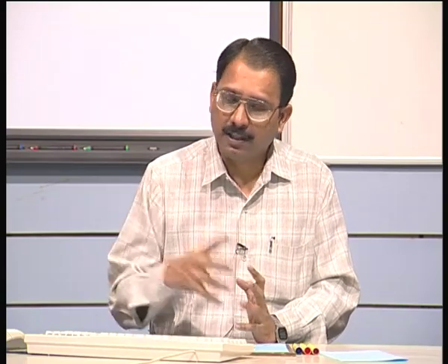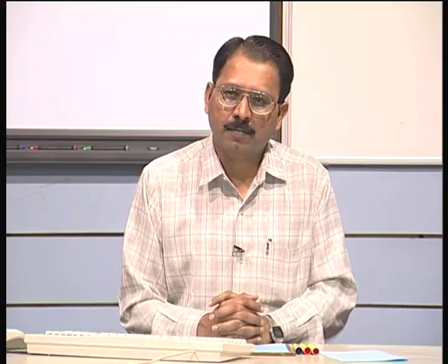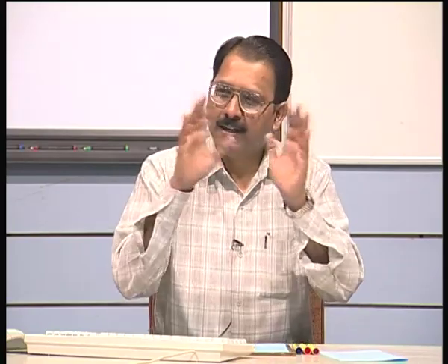So, there are situations where voxel based decomposition methods, both octree and voxel, have many conveniences compared to other methods. Like I gave an example of volume calculation. If I want to know quickly, suppose I have a very complex object which is a free form solid, but I have an octree or voxel representation of that, then calculation of volume becomes just simple multiplications and additions. There is nothing more.